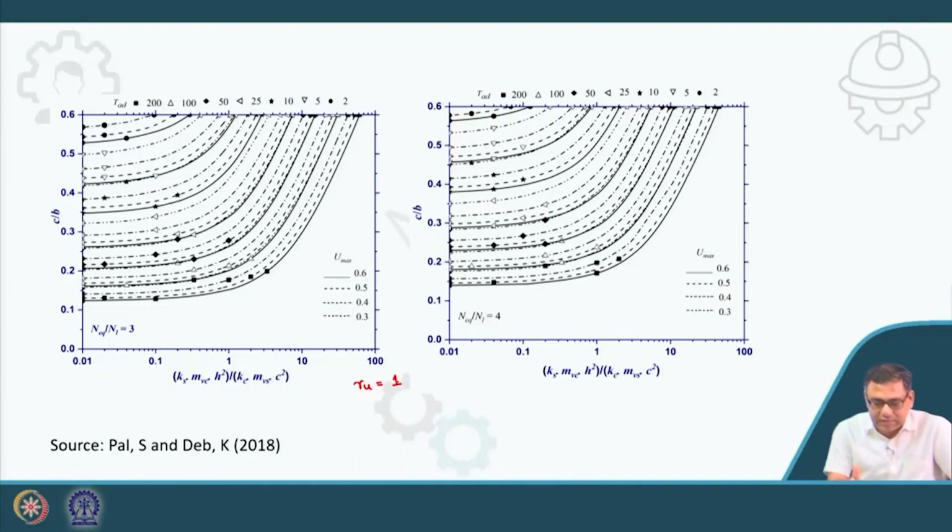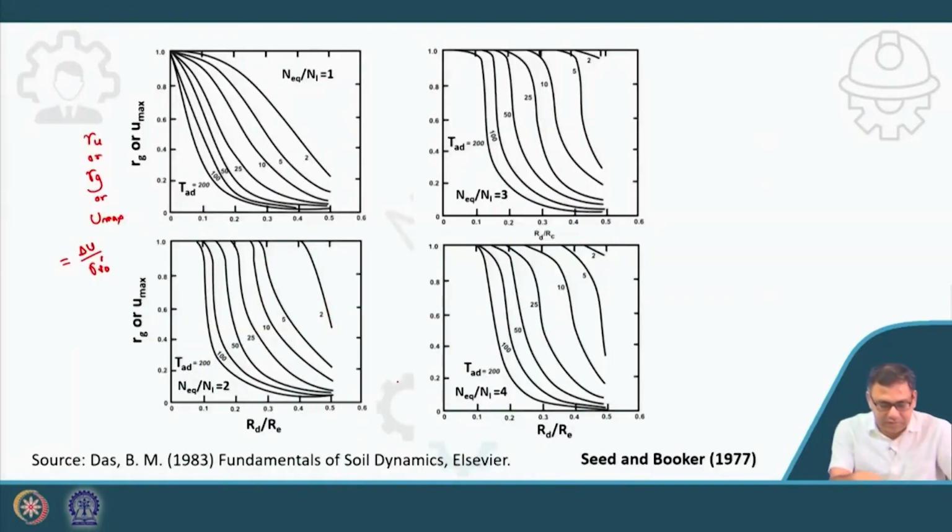So here, that's why charts are given up to 0.6, but here the chart is given for 0 to 1, but you will go maximum up to 0.6, because the rest of the things is your factor of safety, or you will not allow that pore pressure to generate at that level. Your strength will reduce, so there will be a stability issue in the stone column.